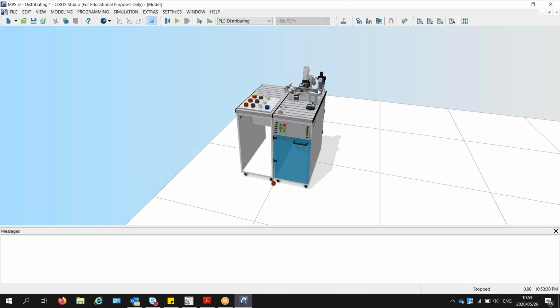If we don't use a delay so that the workpiece falls off of the conveyor, or let us say goes on to the next station, which will be here, then we have a material that's stuck here, and then we start a new cycle where a workpiece comes out, and now you have 2 workpieces on the conveyor. So, not to complicate it too much, we want 1 workpiece at a time on the conveyor. Then we need to delay the off state of the conveyor so that there's enough time for the conveyor to travel up to the point where the workpiece falls off the conveyor.